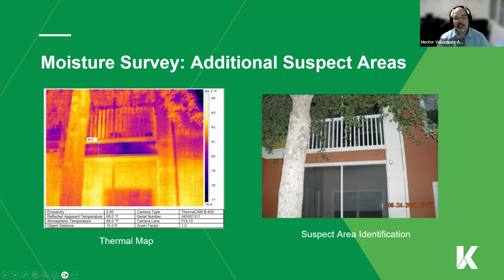That means that water has got into it, and we do have a structural problem that has to be fixed now. What will that require? We're going to remove the guardrails on top. We're going to remove the screen enclosure at the bottom. We're going to take out the stucco in that section and replace that header.